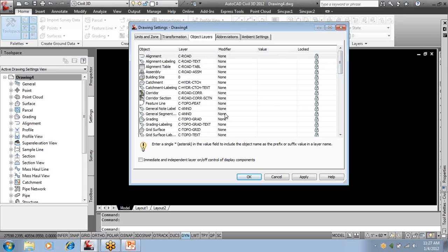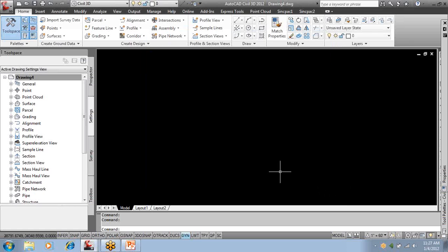If you just grab the AutoCAD template, then there are no layers. The layers, the content, there's nothing built for you. It's almost like drawing in AutoCAD with just layer 0. So to give yourself at least a project to start with, at least start with this template.